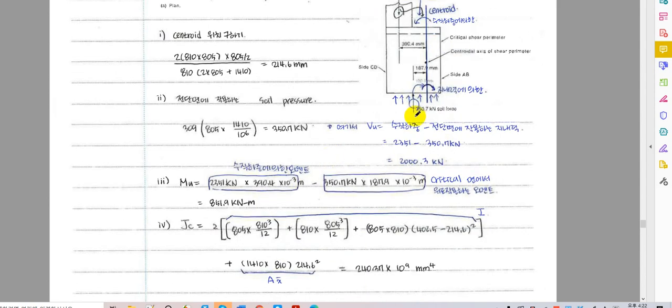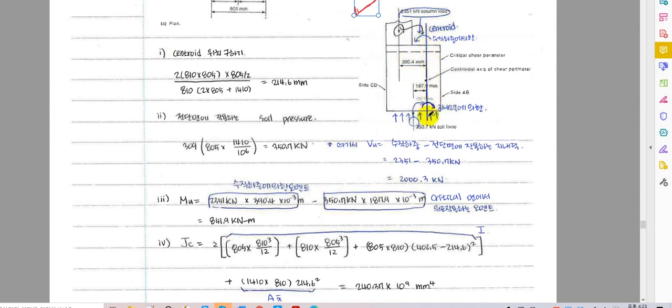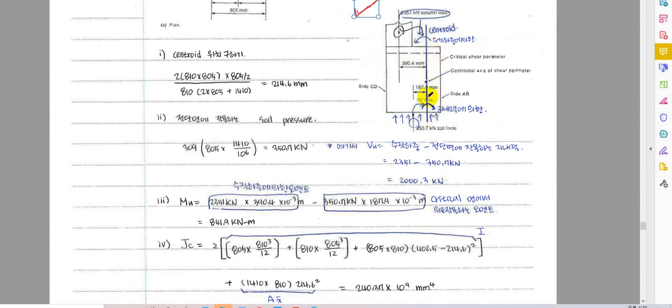We'll just take a look at all these dimensions. The dimensions are very easy: this is the shear center, calculated from the axis of loading, and this distance is from the axis of the shear flow and bearing pressures. So we come up with an unbalanced moment of 851.9 kilonewton meters.